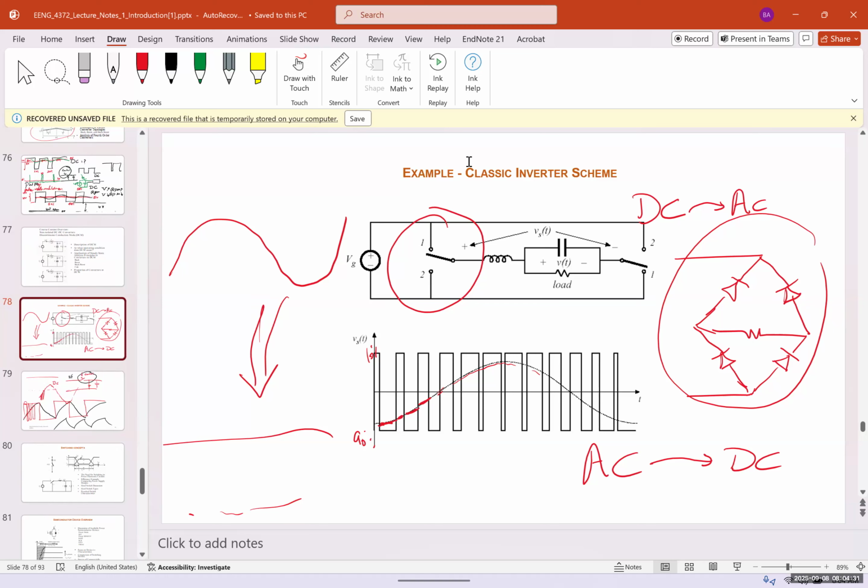I gave an example of the RC cars. If we want to determine the voltage and give it a specific voltage, we can change the pulse width, and by changing that pulse width, we change the average DC voltage, and therefore we can control the DC motor speed.